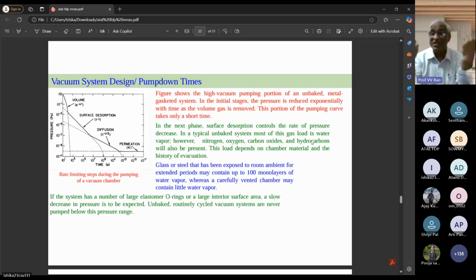So that is called yield strength of that solid material, because copper, stainless steel, they have got yield strength. So between two stainless steel flanges, there will be one flat, one sharp edge that will make a dent on that, because of high stress when you are applying. Instead of having a clamping of the flanges, you need to make the tightening of bolt and nut type. So if you do all that, a typical ultra high vacuum system looks much more stylish compared to a vacuum system. But it's not always required.